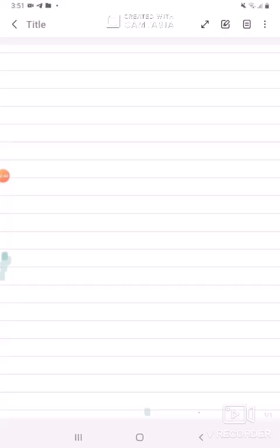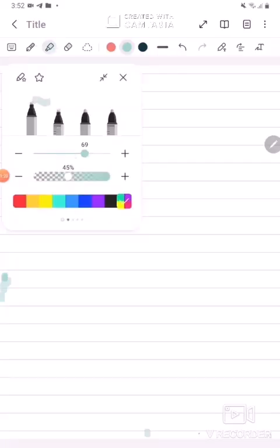First, we discuss the Mohr-Coulomb constitutive model. Mohr-Coulomb is an elastic, perfectly plastic model. It means that the relation between strain and stress is firstly linear elastic, and after that it changes to perfectly plastic. If you want to see, we can, for example, draw that.